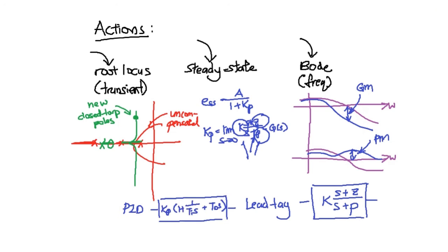You can see that the transfer function of the PID, Kp(1 + 1/(Ti s) + Td s), will result in an effect similar to a lead-lag because of the additional poles and zeros. Okay, I have provided an overview of the compensation techniques that we normally use in classical control theory, and in the next video I'm going to introduce specifically how we calculate or determine the transfer function of the compensator with respect to a set of specifications.